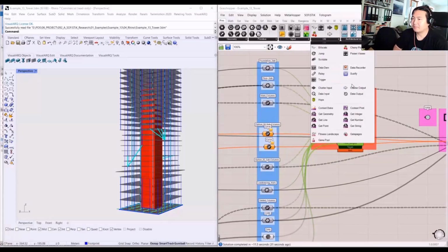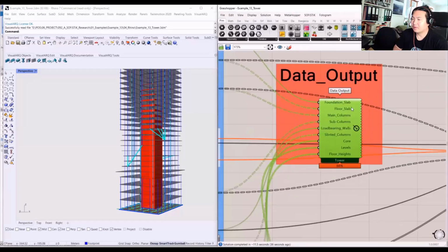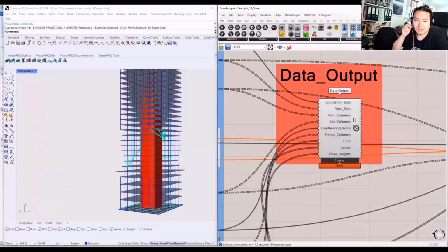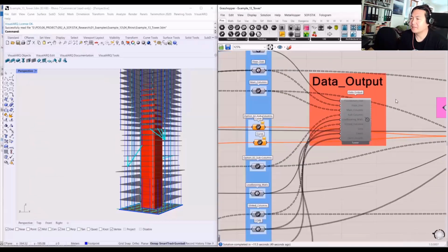And for instance, here I'm highlighting the design data input and output with red color. That's the file that I can save the streaming file outside of this Grasshopper definition, so that we can synchronize for the structural analysis or transferring data into Revit using Rhino.Inside.Revit components. We can avoid very heavy performance from long visual programming script.